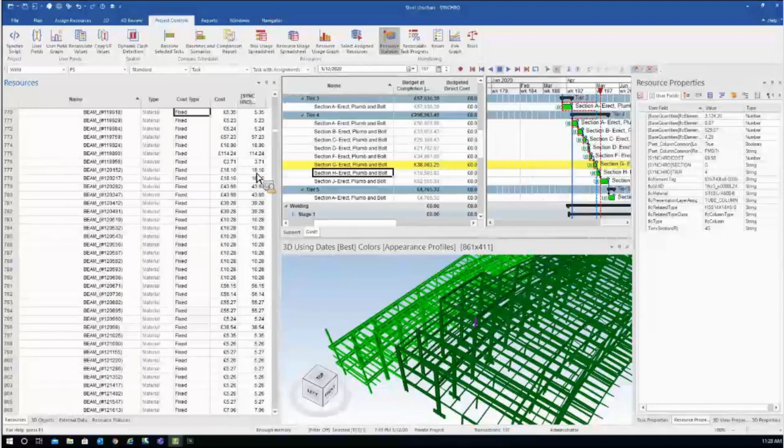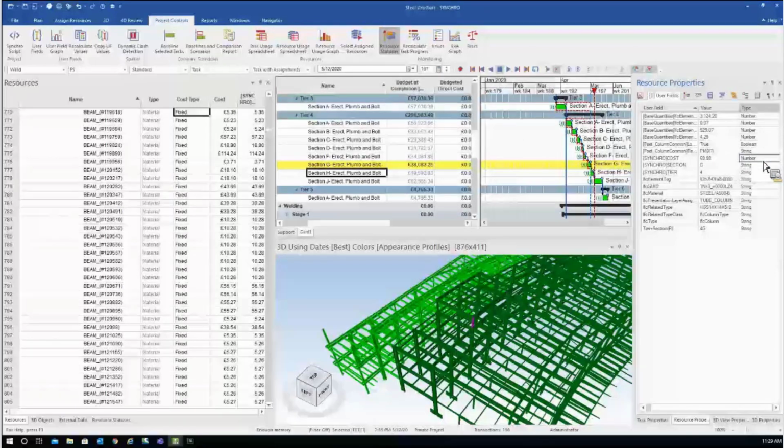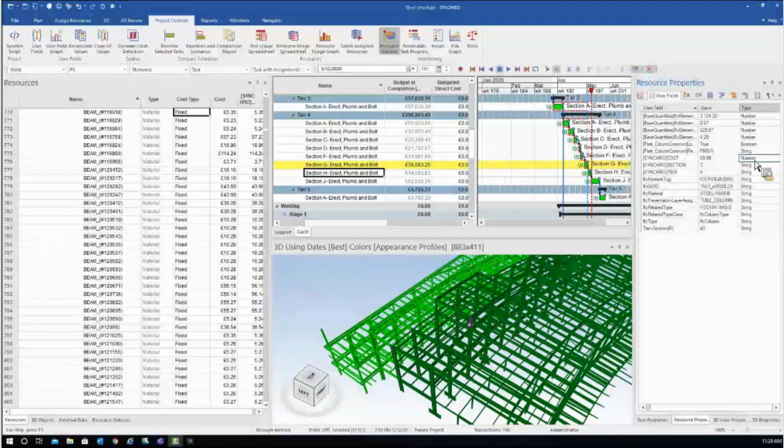And the cost is getting this value. Pay attention here because sometimes this cost user field may come from the 3D authoring software as a string. In this case, it's a number, and it's all fine because the cost property accepts only numbers, as you may agree.